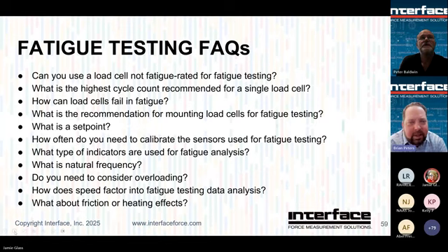Right. What is the highest cycle count recommended for a single load cell? Well, our fatigue rated are 100 million cycles. Yes, and I would say, yep. Yeah, and again, in our 50 plus 60 years of selling load cells, we haven't had fatigue rated 1000 series come back with a fatigue failure. So I think the answer might be unknown at this point for high cycle count. Next one.